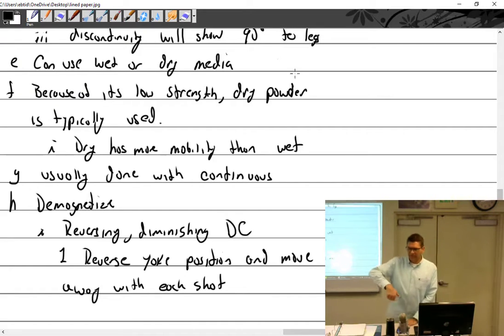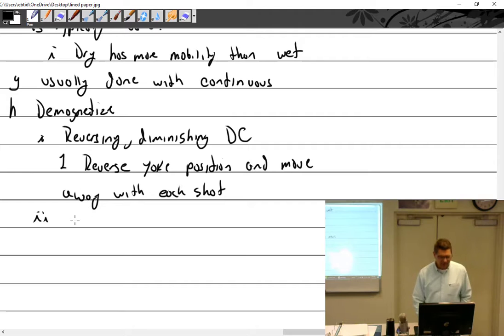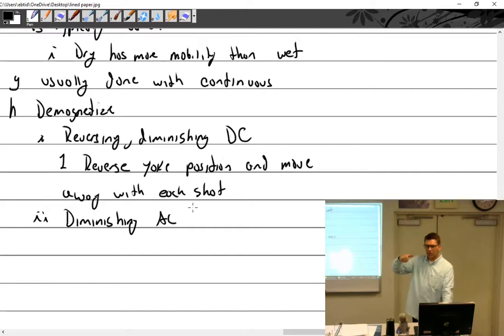So you'd have to pick it up just a little tiny bit and rotate it, hit the button, and then what's going to happen when you do that? The part's going to jump up and hit it, and you got to start all over again. So you got to hold it down if it's a plate or something. But if it's something mounted, and if you're using this on a bridge, the bridge isn't going to move. So you just go back and forth each time and kind of walk away from the part. Do you constantly hold the button, or do you pull, press, release, press, release? I prefer AC, just diminishing AC. Turn it on and just slowly pull it away, and you're done.